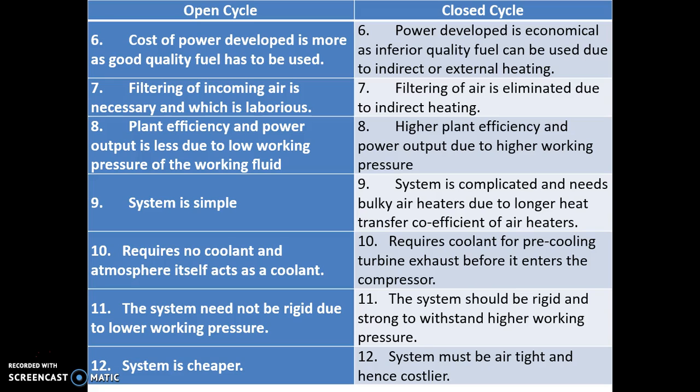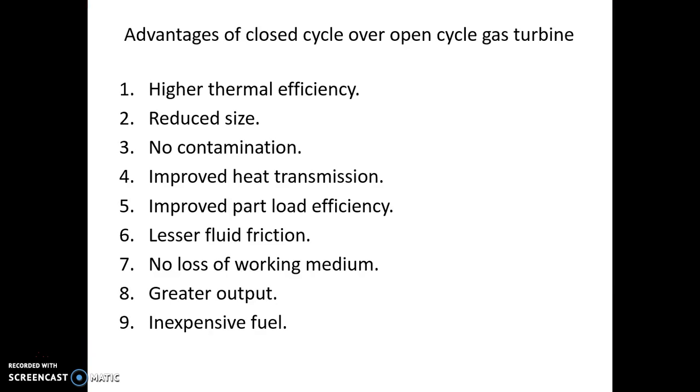And the open cycle requires no coolant, and the atmosphere itself behaves as a coolant, but in the closed cycle we need a coolant before entering into the compressor. The system need not be rigid in the open cycle because of the lower working pressure, but in the closed cycle, if you are using higher pressure, it should be robust. And the open cycle system is cheaper as compared to the closed cycle system.